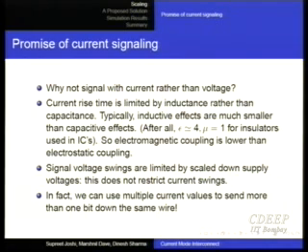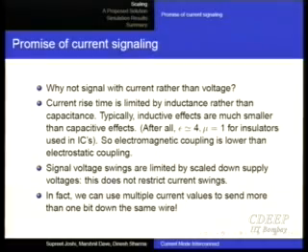That as the technology changes, voltages are scaled down further and further. Therefore, the headroom in voltage shrinks as we go to higher and higher technologies. And therefore, each delta V will become even smaller and become comparable to noise. Okay? So then you say, okay, why doesn't that apply to current? And the answer is that whatever the voltage, you can still design circuits which will have large amounts of current. That is not being scaled down.